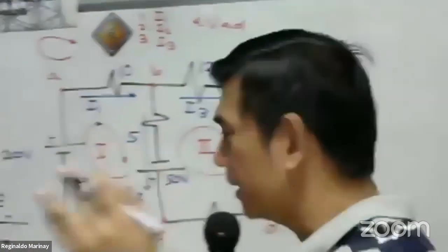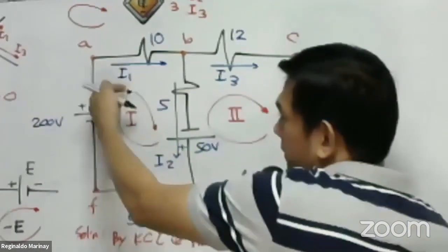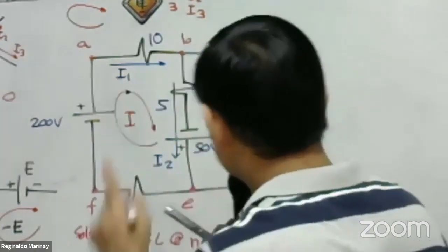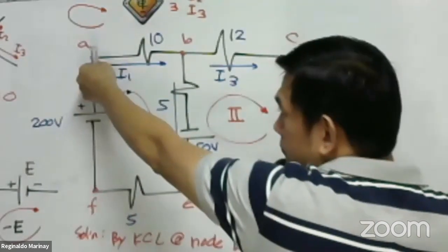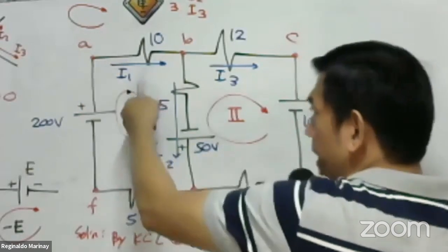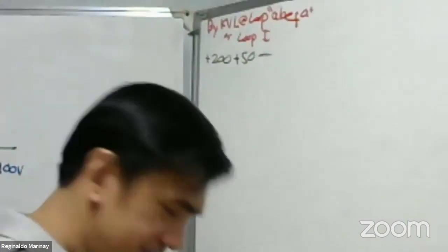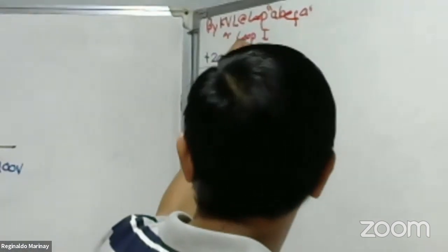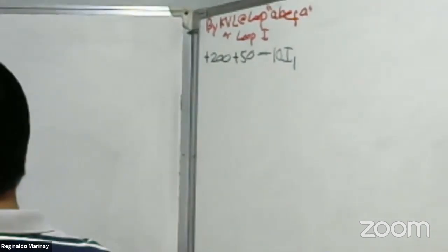If there is only one direction of the circuit current and the tracing, circuit tracing, they have only one direction, one line. If there are two directions, two lines. Later, we'll discuss that. Let's go first with one direction. I1 to the right. Circuit tracing to the right. So therefore, put here to the right. So meaning it is negative. Okay. So we have here 10 I1.